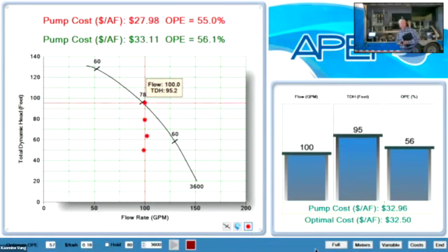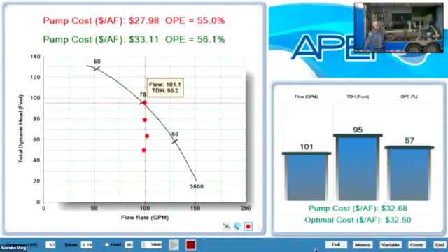Now we're at our full speed. There's nowhere to go from there. But every time I increase the speed, the energy into the pumping plant increased too through the VFD. Now we're at full speed again, and we're pulling 4.69 kilowatts, back where we started, even a little bit higher because there's more pressure or something. Anyway, we're back to where we are. Now we're more efficient, but every time we do this, the cost went up because we're having to create that extra pressure. This is kind of an example of what guys are doing.